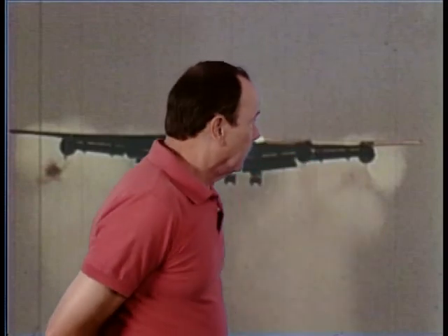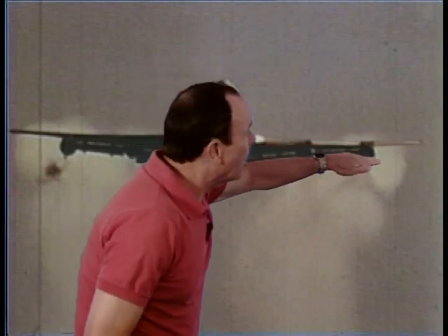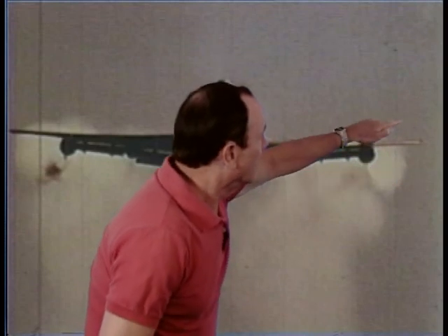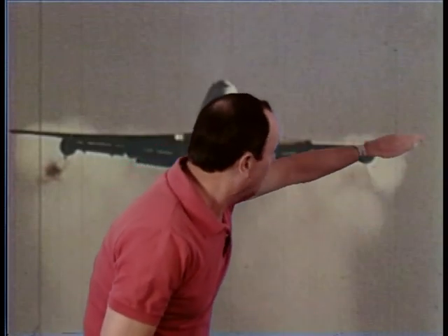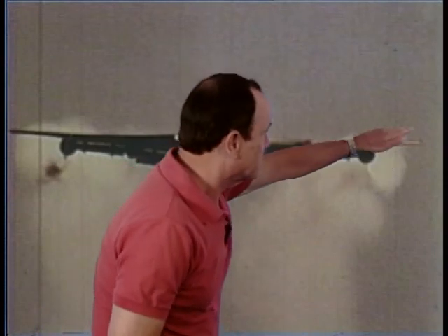Now, we said earlier, when a wing is producing lift, there's relative high pressure underneath the wing and relative low pressure on top of the wing, and what happens is the air actually tries to make its way around the wingtip to destroy the lift on the top of the wing. They call these wingtip vortices. The air does make its way around the wingtip, and it does destroy lift on part of the wing. So some of the lift is being destroyed out at the wingtips due to these wingtip vortices.